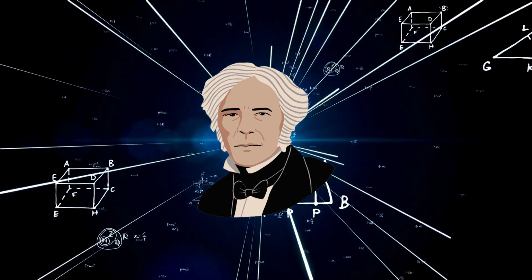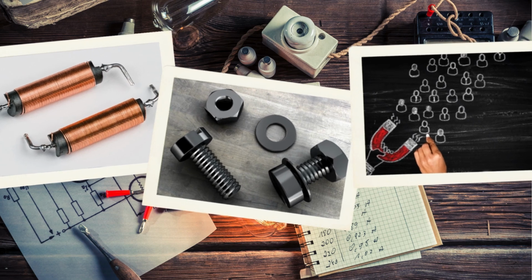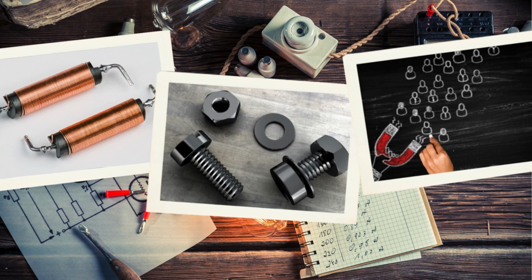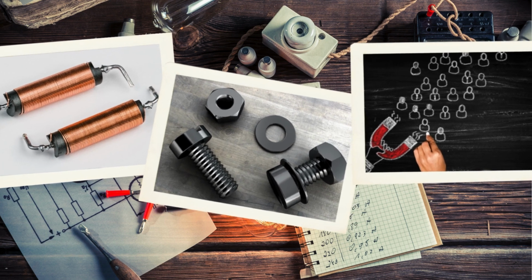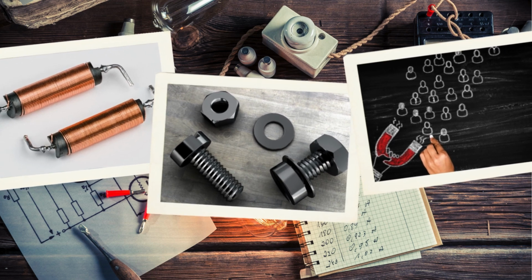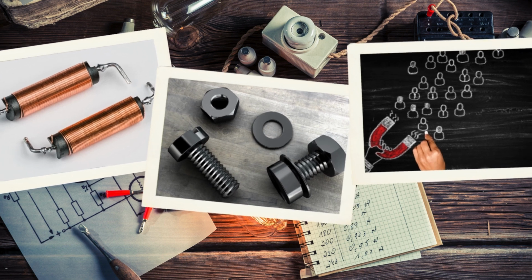Lastly, here are some tips for the experiment. 1. The faster you move the magnet through the coil, the greater the induced voltage will be. 2. Make sure the magnet passes as close as possible to the core of the coil. 3. Inserting an iron core can increase the inductance and, consequently, the induced voltage.